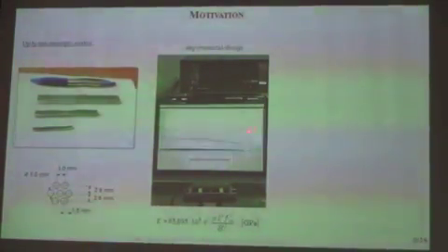You get the eigenfrequencies of the system. Here are 4 eigenfrequencies, and a very precisely calibrated frequency measurement machine gives you the first eigenfrequency. Out of Euler-Bernoulli beam theory, you can in the end calculate Young's modulus. Therefore you need to know the density of the material, the length is very important, the first eigenfrequency you measure, and the thickness of the beam.